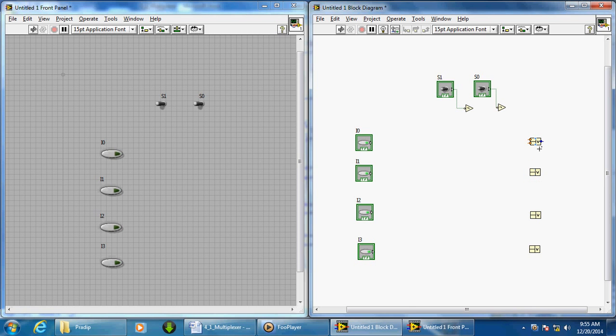Okay. Now we need 3 input AND gates, but here it is only 2 inputs, you can see. So if you drag this down, it will give you one more input. Here also we'll do the same thing, one more input, and here if you drag down, then it will give you one more input. So now it has become 3 input arithmetic functions. Now you have not defined that this is an AND gate.